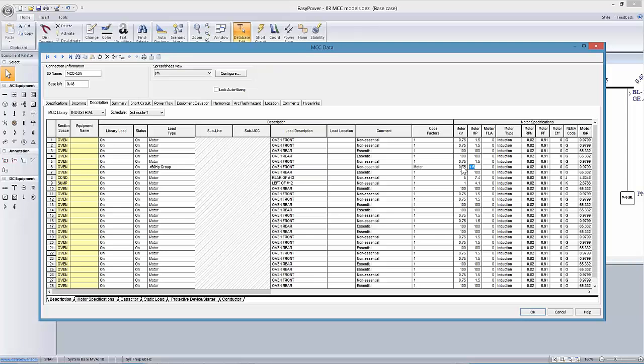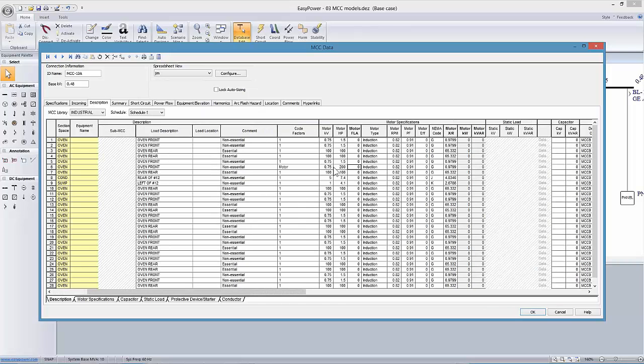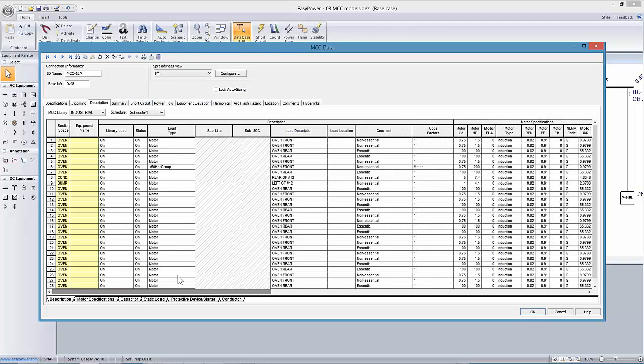Let's say it was 200 horsepower. Let's say we had 10, 20 horsepower motors. By doing this, we would have the ability to consider, again, a less complex example and accommodate the calculations for incident energy at the main bus level. So this is not only allowed but recommended in arc flash application of IEEE 1584.